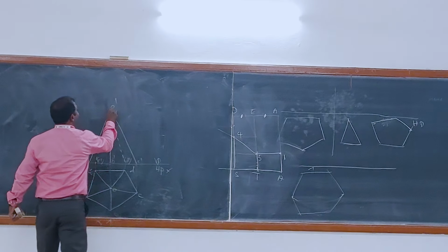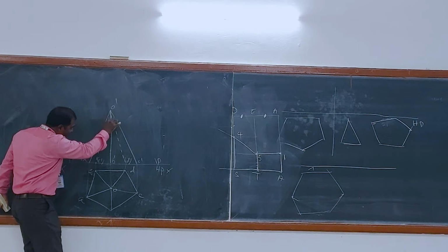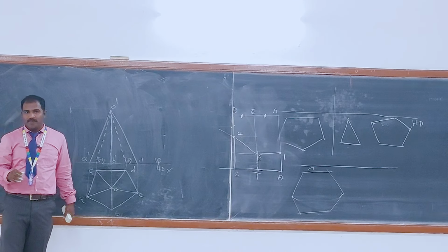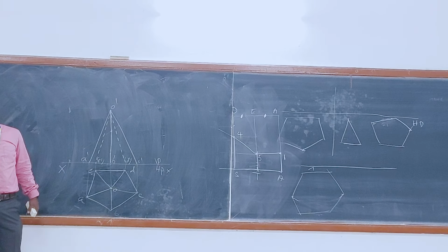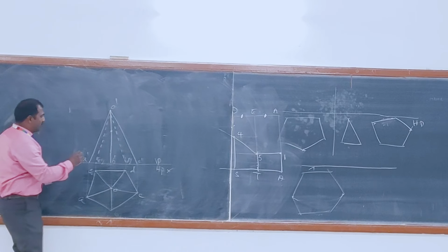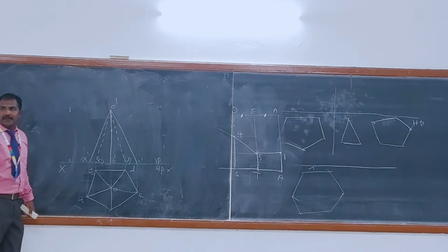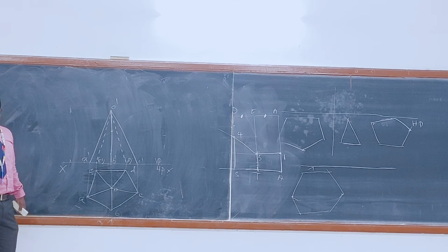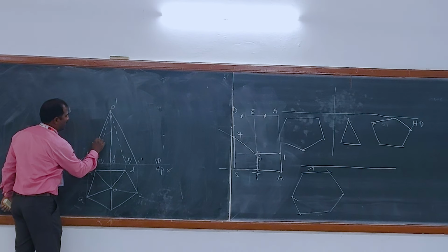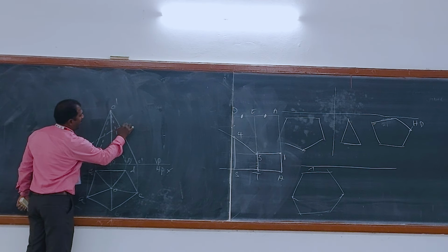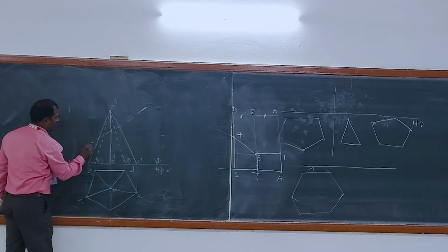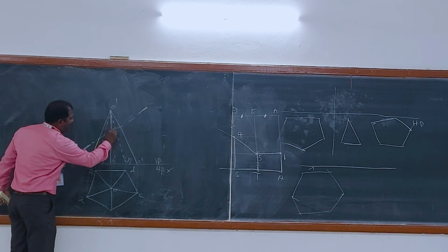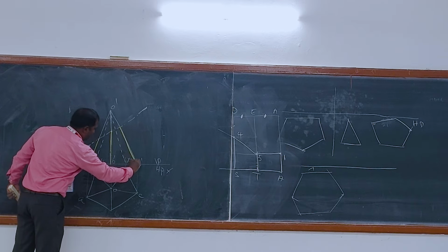So this is our apex, right? Now from the apex we take 20 mm. At this place we have to draw a 55 degree line. Got it? So I will draw, okay? Should we cut the base or not? No, we can cut the base, right? Okay. Mark the remaining solid. Mark all the remaining solids. That's very, very important.